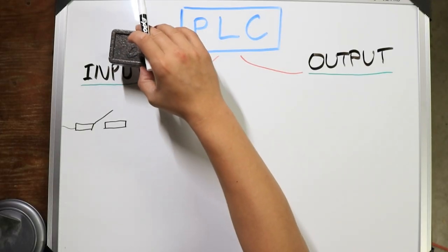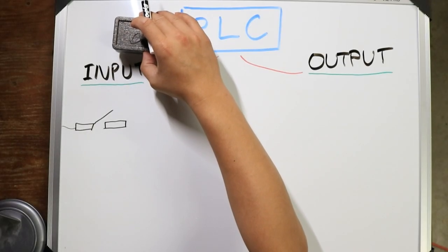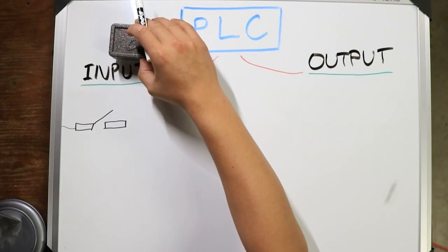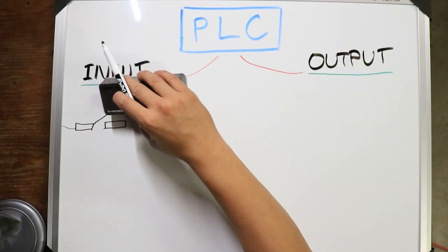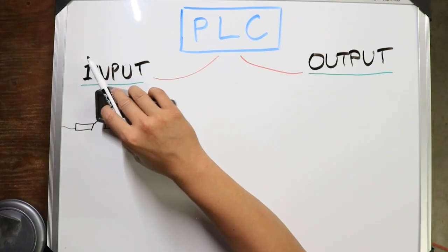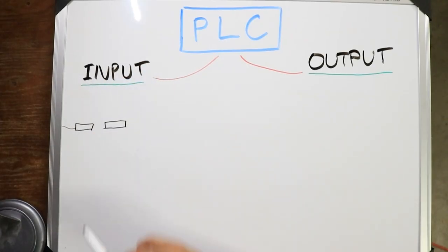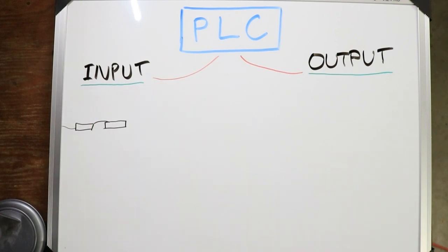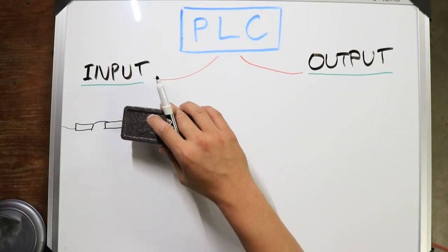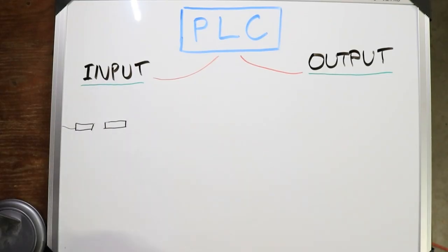And same concept. Let's say we have a pallet and we want to use a mechanical switch. The pallet comes, it physically hits this lever right here. When it hits that lever, it moves it down and creates contact with the other side to complete a circuit. When it completes a circuit, it turns on. So it was off in its normal state when nothing's touching it.